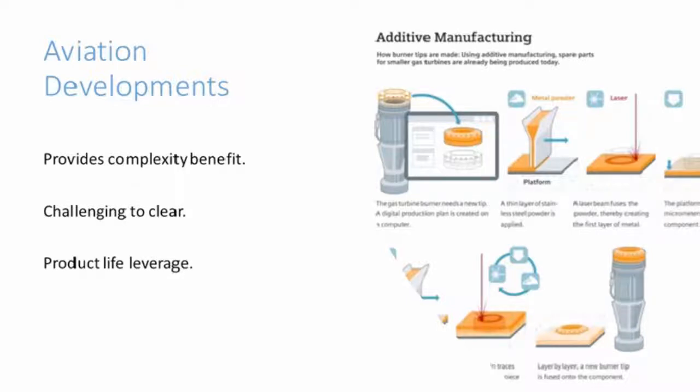Being able to repair existing gas turbine combustion chambers by printing a new tip on reduces the repair time for certain models by around 90%, because the replacement part no longer has to be laboriously welded together. Instead, the burner tip is simply printed onto the body of the burner, reducing repair costs considerably.